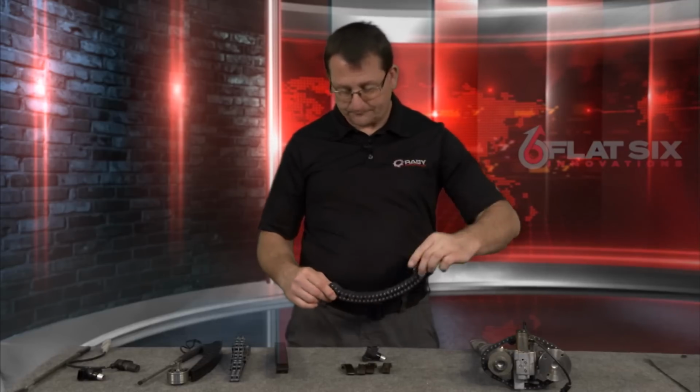But there are some things further out in the valve train that can make that wear become worse on bank 1 or worse on bank 2. But if you see an engine that's got like 2 degrees or 3 degrees of retarded type valve deviation, camshaft deviation, negative numbers that is, then usually this chain is responsible for that, okay?